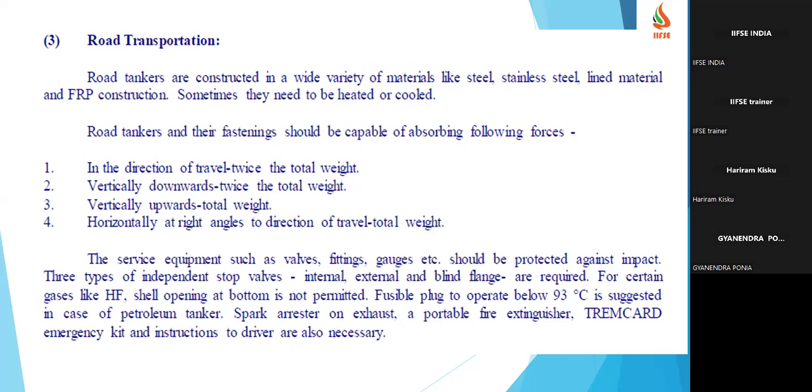So in those situations also, the vehicle should be able to manage the weight of the material as well as the truck weight. The service equipment such as valves, fittings, and gauges should be protected against impact, and three types of independent stop valves, internal, external, and blind flange, are required. For certain gases like HF, hydrofluoric acid, shell opening at the bottom is not permitted, and a fusible plug to operate below 90 degrees is suggested in case of any petroleum tanker.